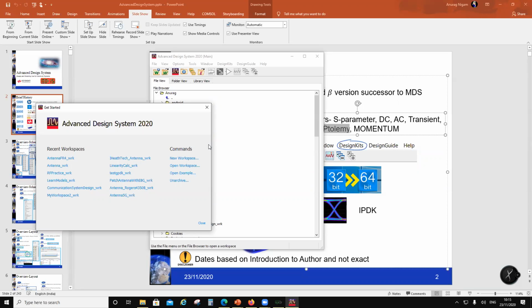So now a nonlinear system can be split up into linear systems at different frequencies, right? Fundamental and harmonics. And you can solve the circuit for that. And then the principle of superposition will still apply. And you should be able to construct back your waveform from a nonlinear system, right? So that's what harmonic balance or Volterra series is.